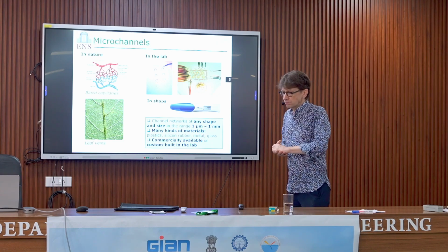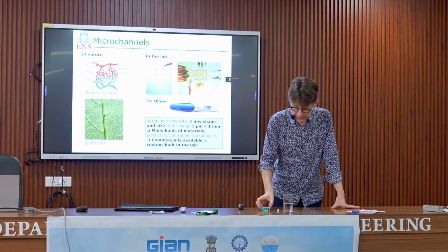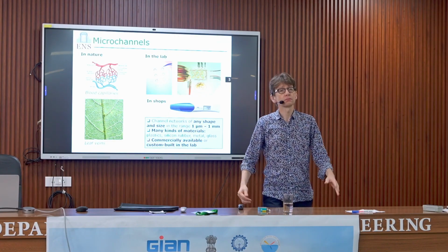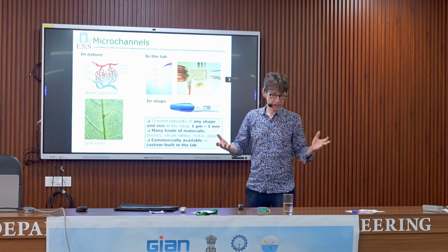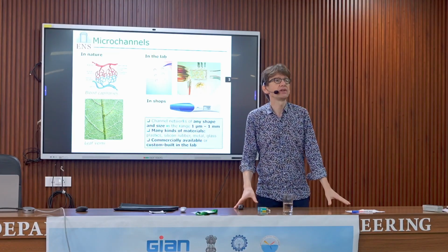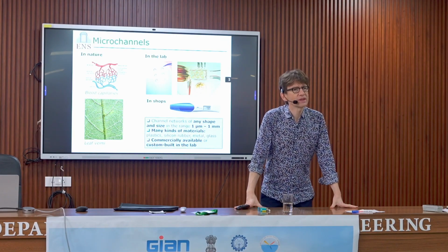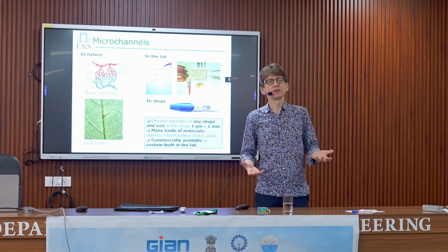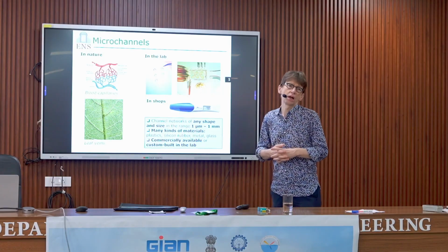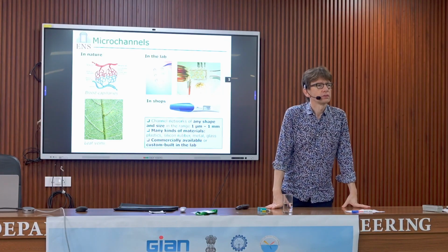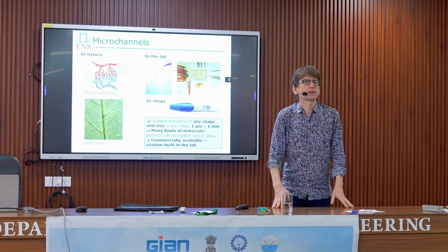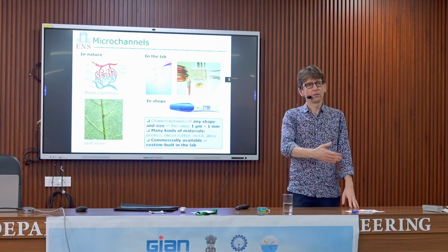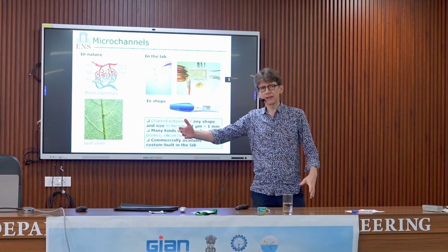So what you should remember about microfluidics is that currently we are at a stage where there is no big challenge in fabrication. You can fabricate practically anything you want as soon as you are above a micrometer. It's a bit more challenging when you reach 100 nanometers. There are methods, but from 1 micrometer to millimeter scale, there are methods.